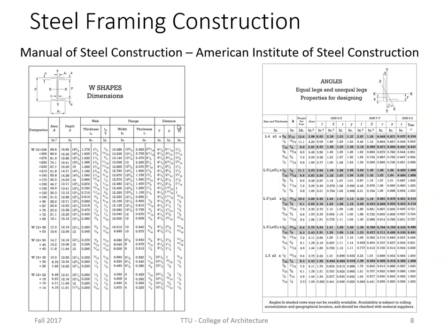Here is a couple of pages out of the American Institute of Steel Construction Manual. And once again, you can see all the ranges of different materials. Just note that the area of the steel is here. That's the area of the cross section of the steel. The depth in inches. So if you're interested in what the depth is, here's the actual depth for that W12 336.